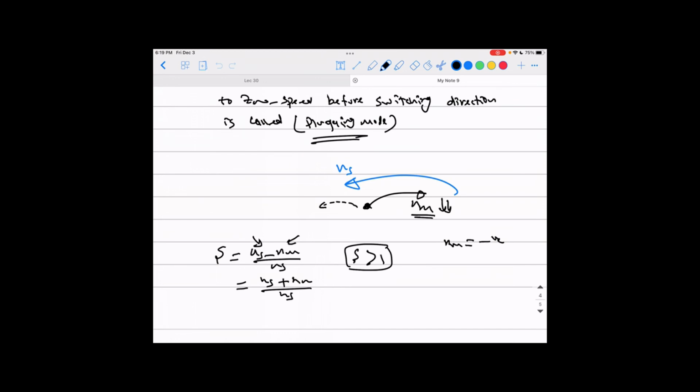Okay, guys? Again, it's some sort of a transient time. It will not last forever. It's just gradually reducing this until they catch up in the same direction again. But during this transient time, you still have this condition, that the synchronous speed and the mechanical speed are in two different directions. Okay, guys?